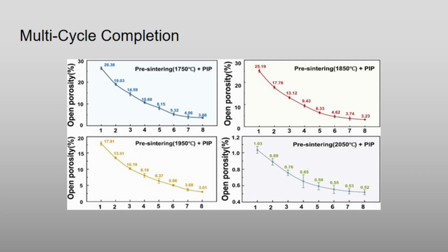This entire loop is repeated 6 to 10 consecutive times until the inner porosity of the composite drops below a strict threshold of 10%. The material data plot below illustrates the precise trajectory of a ceramic matrix composite, reaching multi-cycle completion as a polymer infiltration and pyrolysis sequence repeats over consecutive loops. The physical properties transition from a volatile, highly porous state to a structurally stable ceramic material.